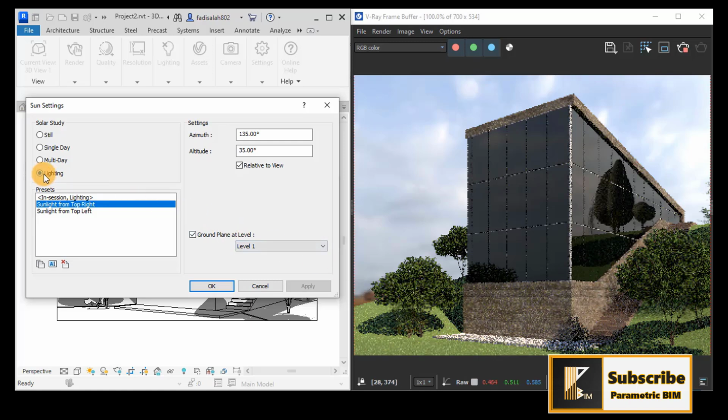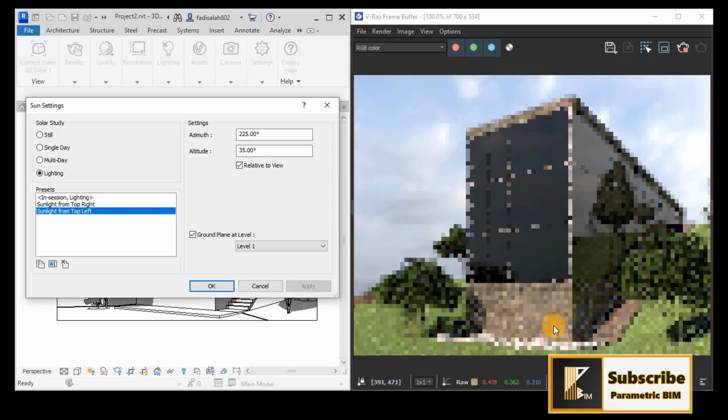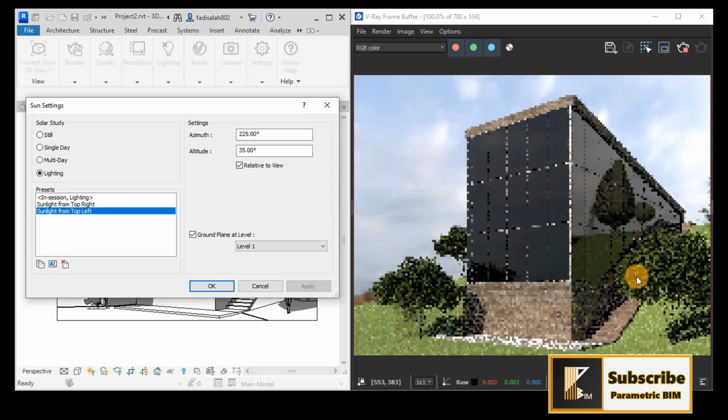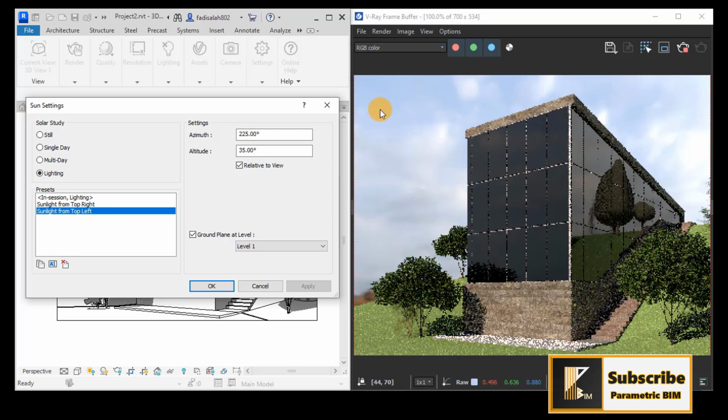And here in the lighting, we have an azimuth and altitude that determine the position of the sun in the sky. But if I come here to the sunlight from top left and apply this, it will re-render, and as you see, now the shadow will be in the opposite direction, because the sun will be at the top left of this image or of the model.